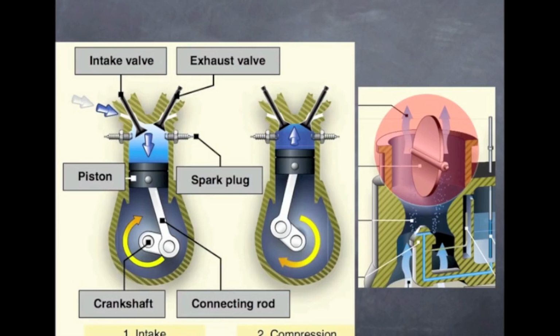But when we decrease our RPM, we are moving that cylinder at a much slower rate. Therefore, less air is being sucked into that cylinder. So therefore, there is a lower negative pressure. Therefore, our manifold pressure actually would start to increase a little bit once we set our RPM setting.